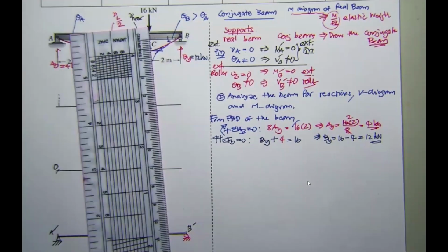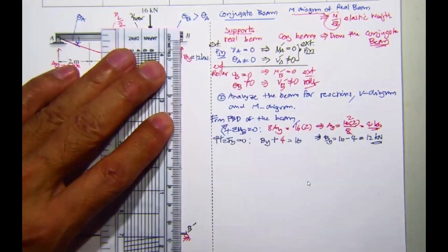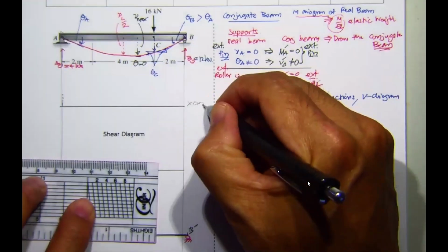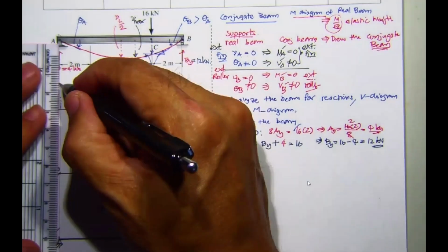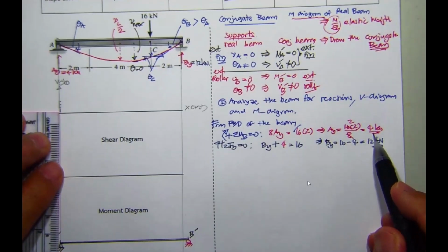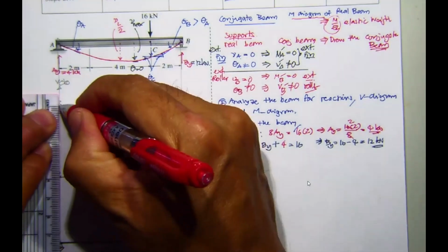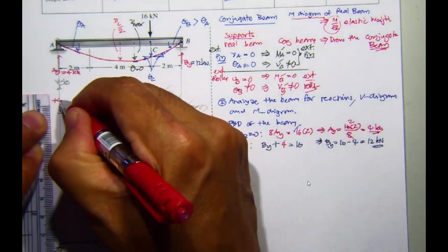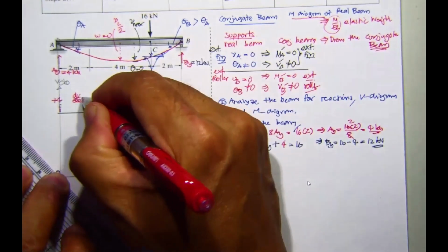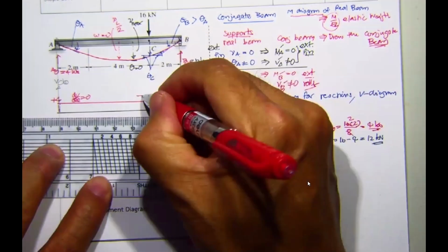You just draw it. As you may know from engineering statics, this is going to be very easy. Take x in meters, and take the shear in kilonewton. You have A sub Y over here to be 4 kilonewton, upward, so plus 4. Then W is 0, so dV by dx is 0. This will be plus 4 up until this point.